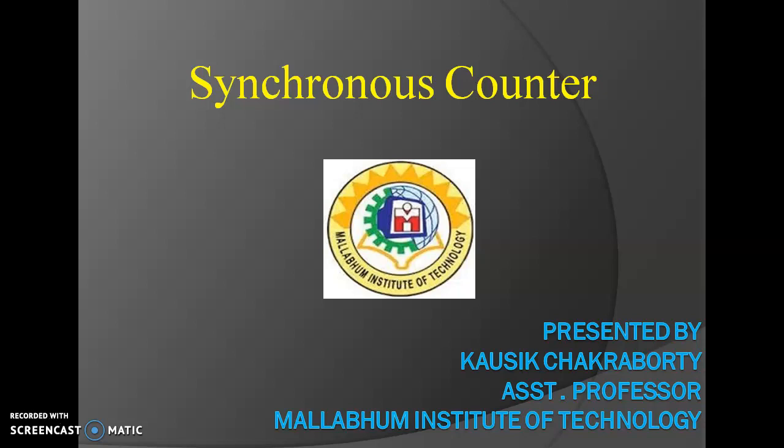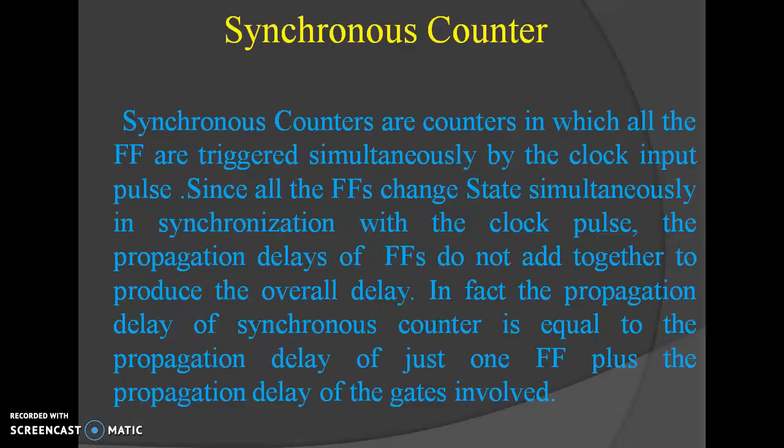In my previous video lecture, we discussed the working principle of ring counter and Johnson counter. Today, we discuss the synchronous counter. We all know synchronous counters are counters in which all the flip-flops are triggered simultaneously by the clock input pulse. Since all the flip-flops change state simultaneously in synchronization with the clock pulse, the propagation delay of the flip-flops does not add together to produce the overall delay.